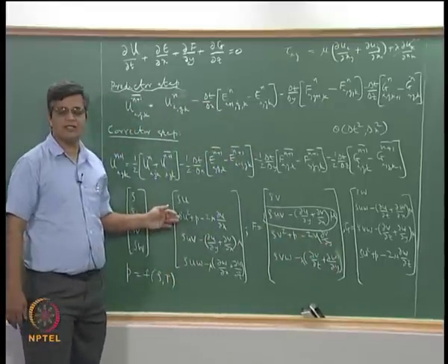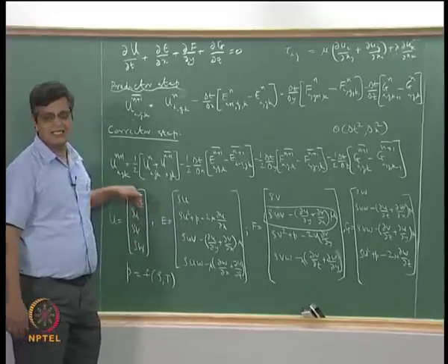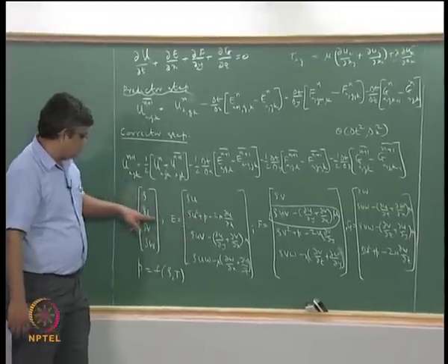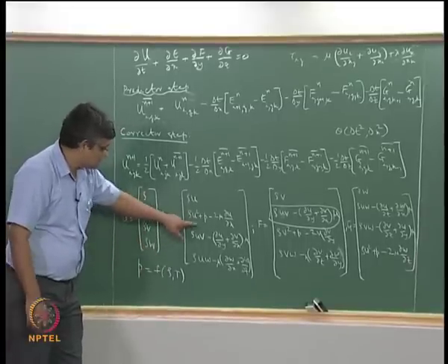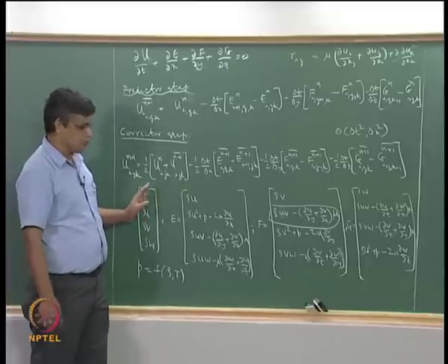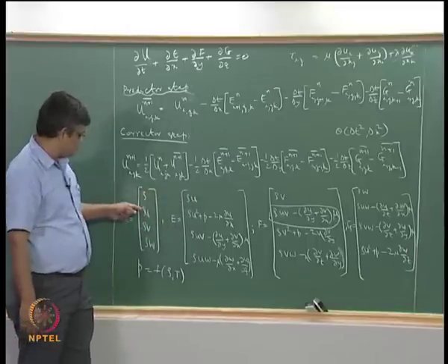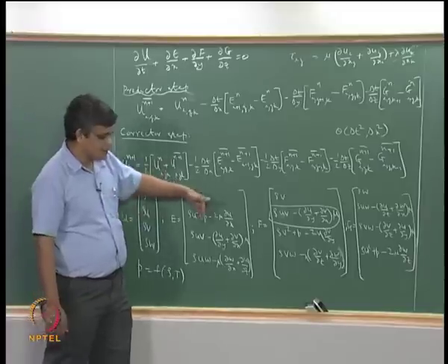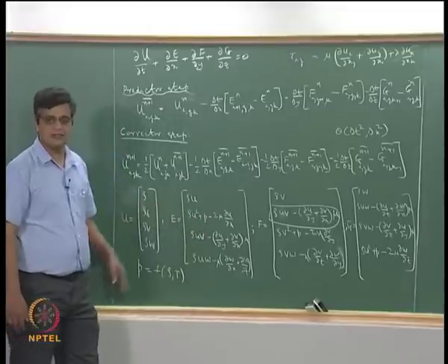Fortunately for us, the pressure gradient is not a function of the variable that we are solving in a direct way. We can see that pressure is influenced by this, and pressure is also given by the density. So in that sense, the source term is nonlinear, but it is not directly coupled to the evaluation of rho u, rho v, rho w in such a way that it appears as a variable in terms of rho u, v, w here.